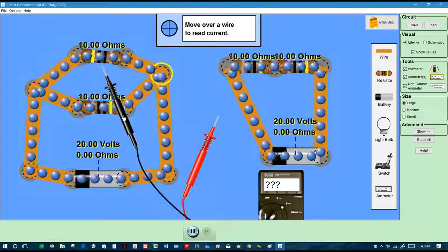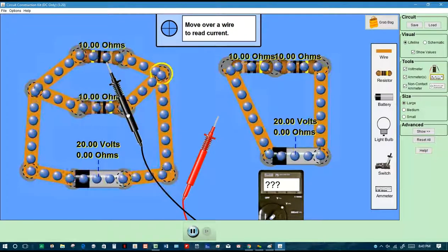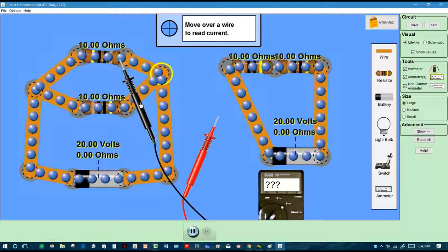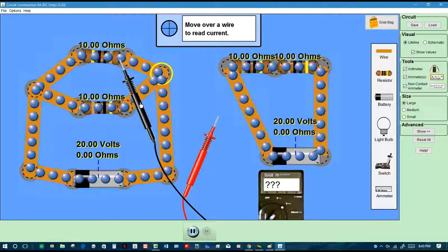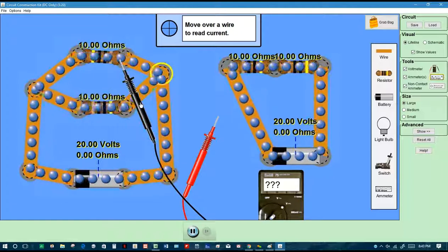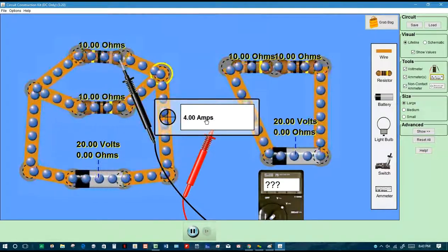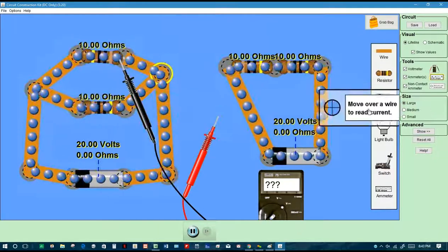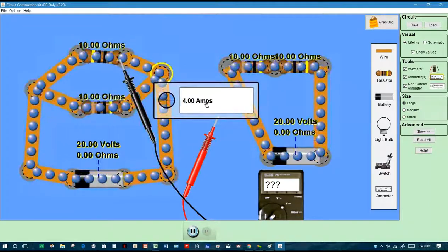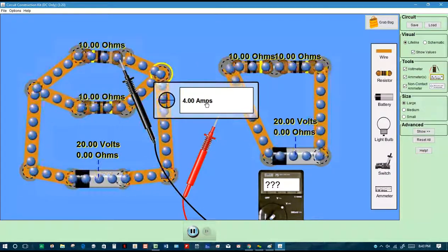Does adding another lane make more resistance to the flow of traffic or less resistance to the flow of traffic? Less resistance. Yes. Adding one more lane provides less resistance because they can flow more easily. They can go into their own lanes, right? This is the reason why there's more current over here, 4 amps, because the resistance of a parallel circuit is less than the resistance of a series circuit, because there are more paths over here. That allows them to speed up. So that's a big idea.